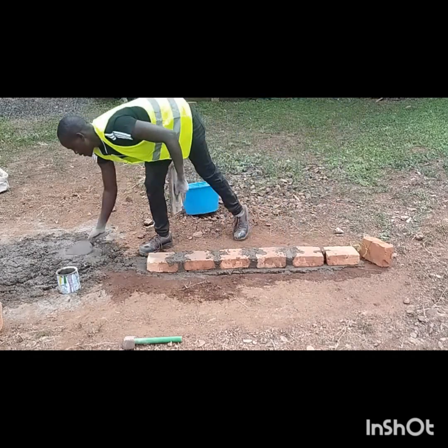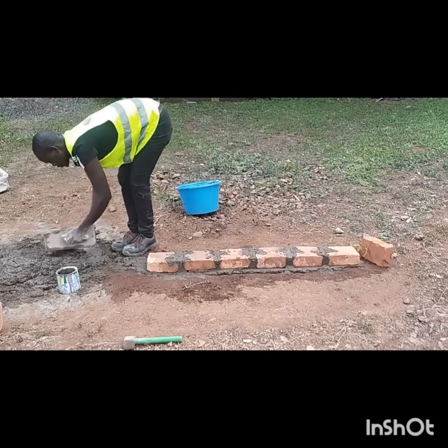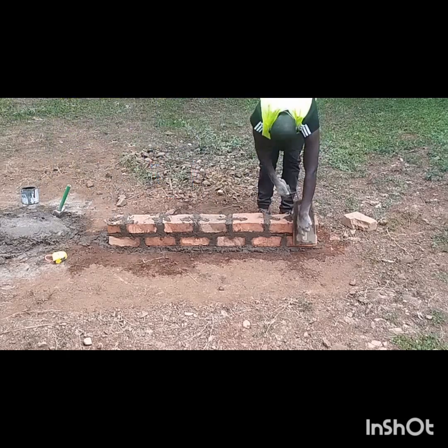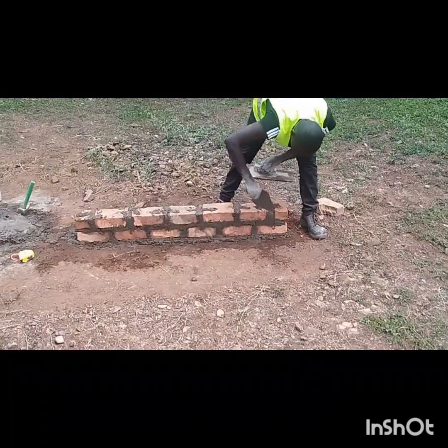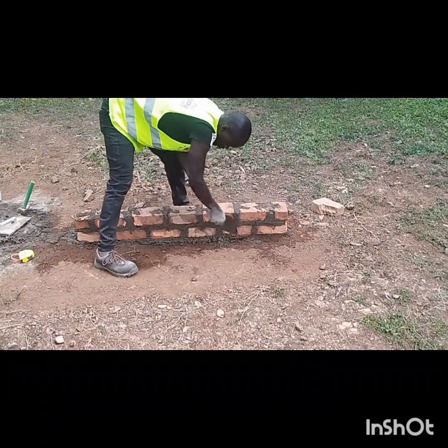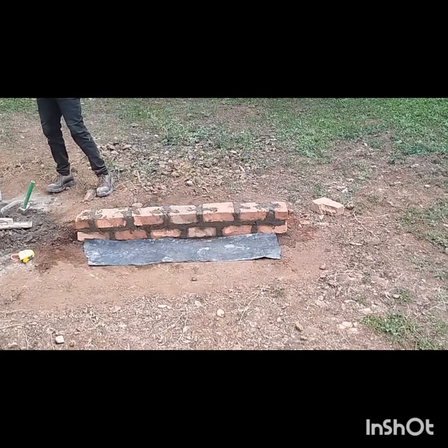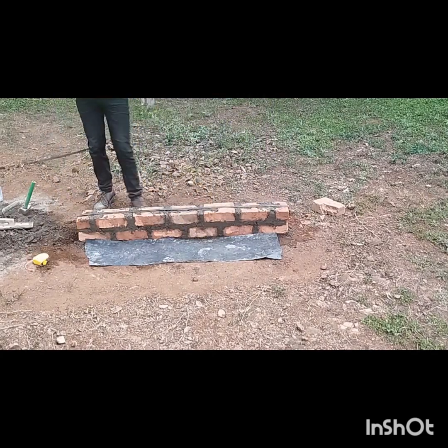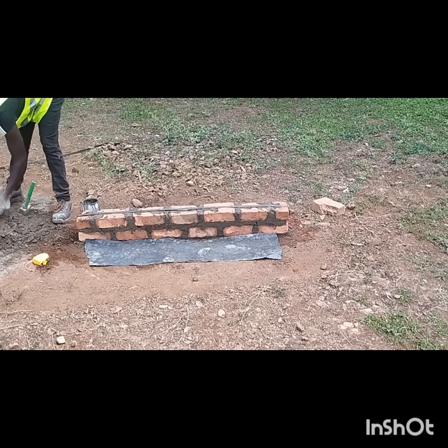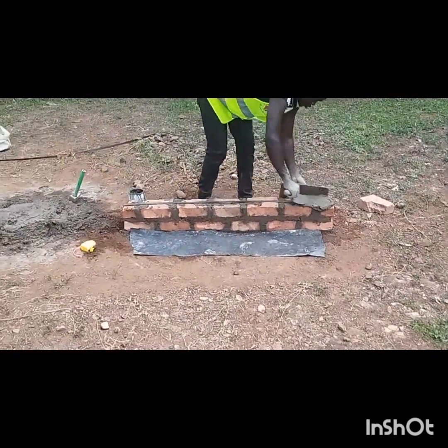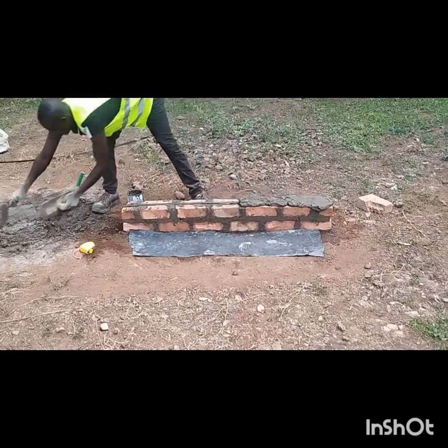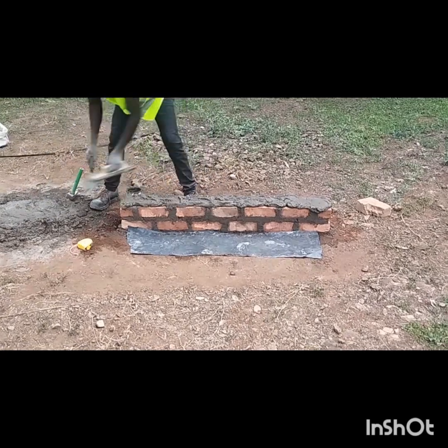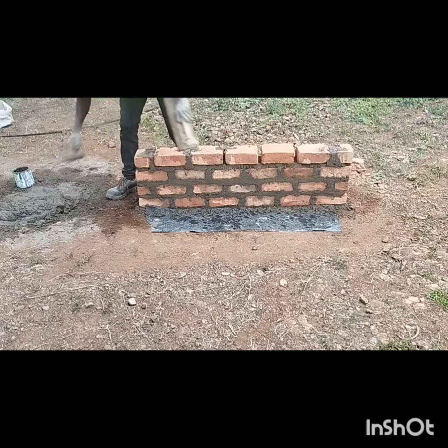This is just to help us in the comparison so that we can see the difference in terms of mortar for the brick wall and for the block wall. The joint also, we are doing the same. We're also putting in hoop iron. In this case, we were putting it after every 2 courses, just to help us in spreading the load and avoid point loads and things like cracks.